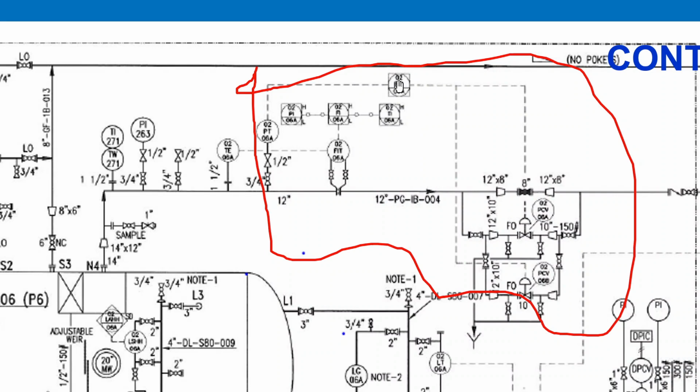It compares the set point with the input process variable reading, then produces an electrical output equivalent to the adjustment needed. That deviation output goes to a control valve.